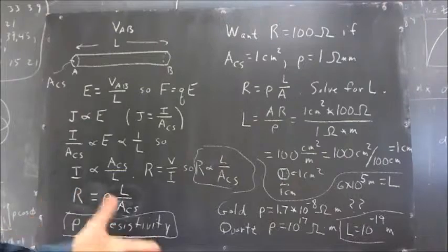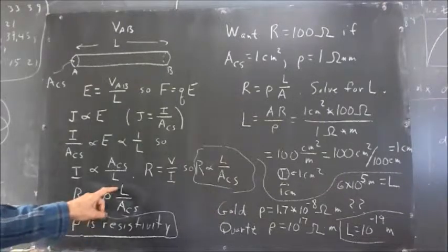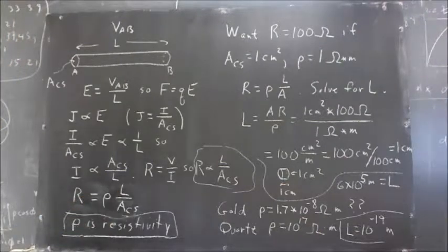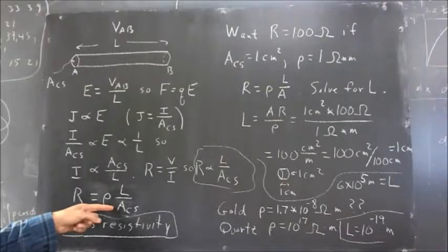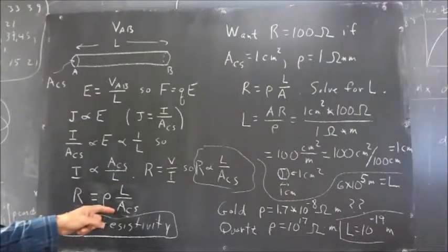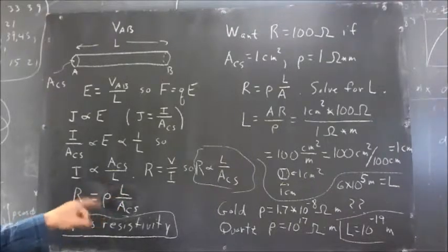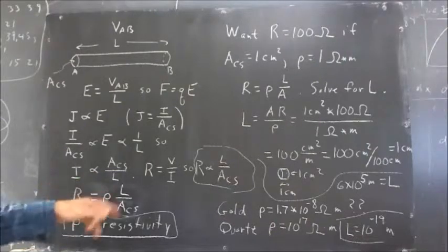first of all, just to give you a little context, you know that the resistance of a piece of nichrome, you experience this directly in lab, was greater if you had a greater length. Now, we didn't actually get to verify that it's also less if you have a greater cross-sectional area, but that is the case. So the resistance is length divided by cross-sectional area times resistivity. And all these are nice and linear or reciprocal linear. And we're going to see why.